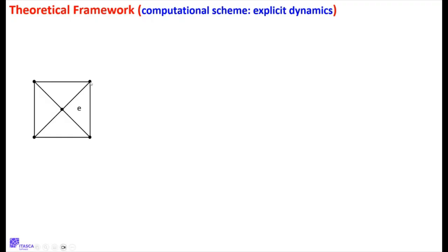So here we go. Here is a shell structure that's a square, and it's been discretized, in this case, not into particles, but into elements. These are called elements, and this is something called finite element approach, where you take a continuous structure and you perfectly discretize it into different shapes, and then those shapes are perfectly connected along these edges. So the edges are just like contacts in PFC. You could think of this as 4 rigid blocks, and there's a contact model here. And basically, a continuum code is the same exact concept, except this contact model is a bit more sophisticated because we're talking about stresses and strains here.